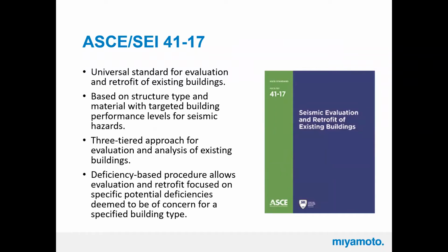ASCE 41 really is the universal standard for both evaluation and retrofit of existing buildings. There used to be two versions: an evaluation document, and then the seismic improvement piece, and they've since combined it into one document. That's the backbone of a lot of the work that we do for assessment. It does have a three-tiered approach for doing the assessments, and we'll talk about that in an upcoming slide. It also has targeted performance levels, and it also contains